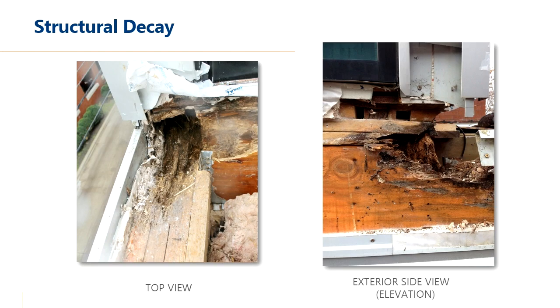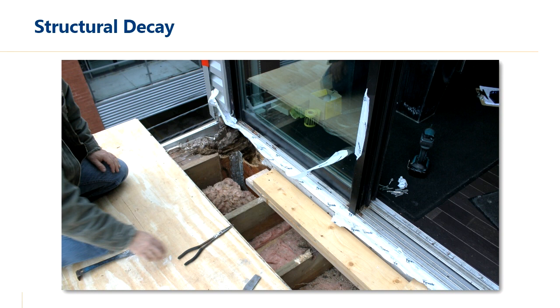And these are some of the photos of what we uncovered at this location. The extent of decay in both the beam, the girder, and its connection were significant and starting to create deflection of the wall above. One thing I want to highlight here is that the load paths were not very easy to deal with. There was not a column below. We ended up adding several columns to this building to facilitate repairs and replacing a lot of elements due to this extent of decay.